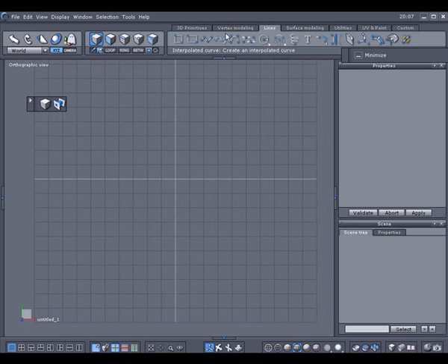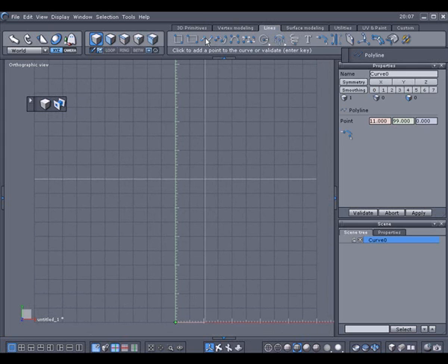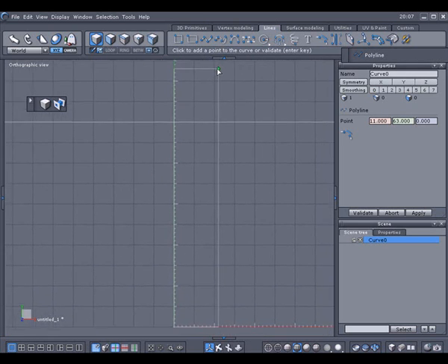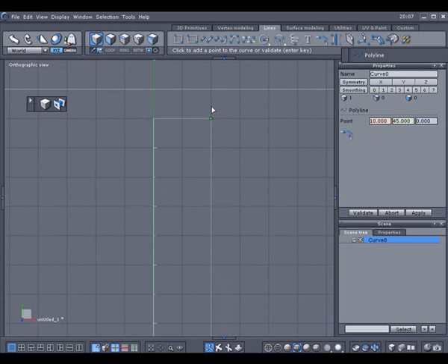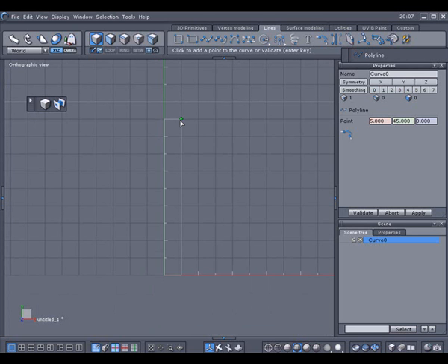So we're going to go ahead and select a line and polyline, and I'm going to click. If you notice here, here's the feedback grid, and we can adjust that by the numpad with the plus and minus key, how much we want to add or how much we want to decrease. So I'm going to add some, then I'm going to decrease some. And if you notice the grid in the background there, or the floor plane grids, I like to space mine out equally to the size of them, so that looks good enough for me.